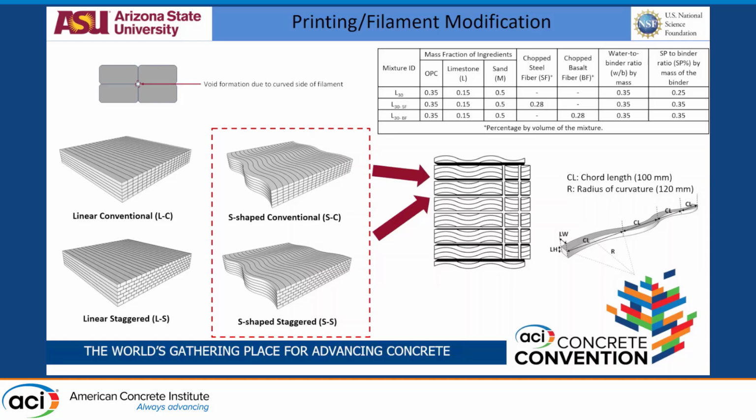While printing, the thing of importance that we see is usually around the places where you have layers and filaments. When I say filaments, it's a print bead. At those connection points, you'll usually see smaller voids forming. As the layer height goes up, you'll see those voids being significant. At lower heights, they might not be as significant, but you usually see these voids. And we all know that in printed systems, these are slightly weaker than the usual cast system because of the interfaces that are formed, the interlayer and the interfilament interface.